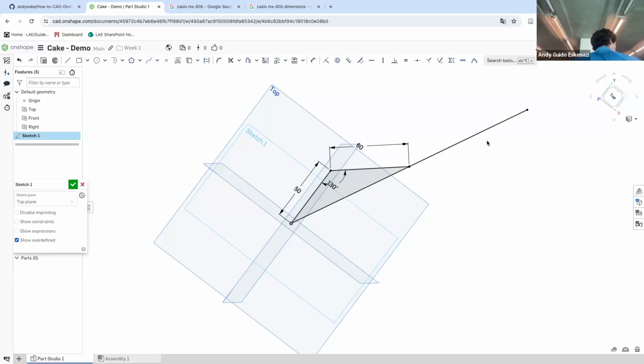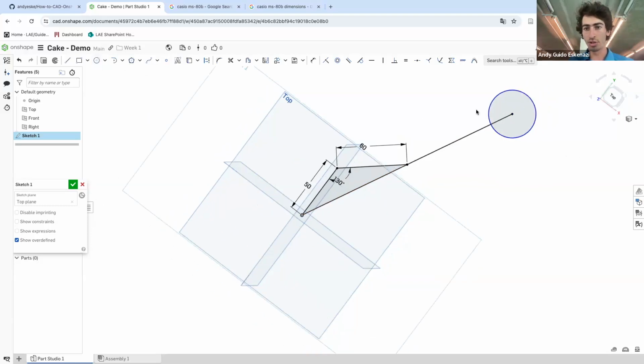But it's important to introduce it now because you'll see, I'll use it a little bit today. Some other things that I can do in terms of constraints is that I can say, draw a circle. Now I'm going to click in that command. I'll draw a circle here, click on D. I'm going to give that some dimension, say 40.